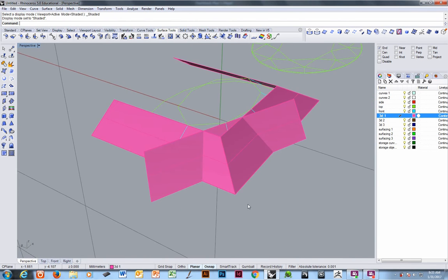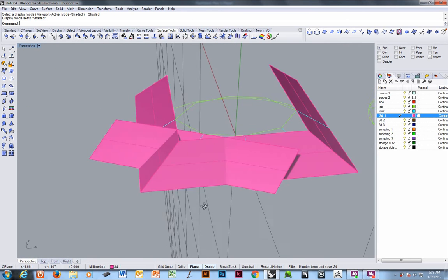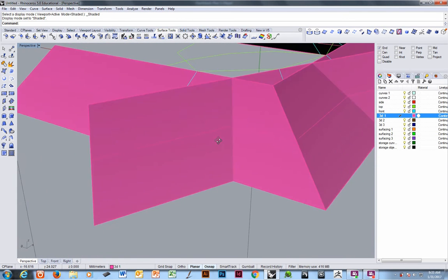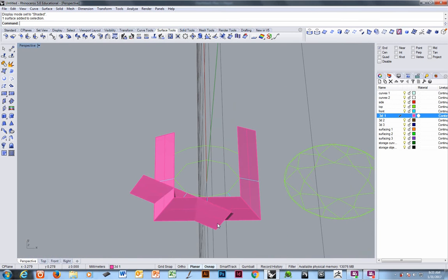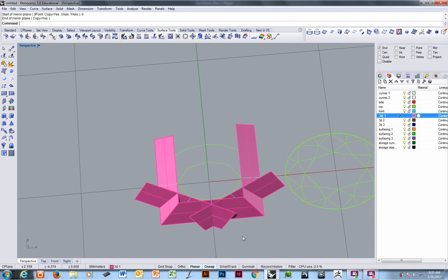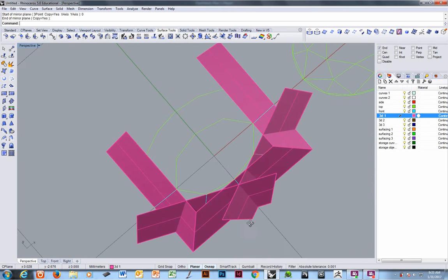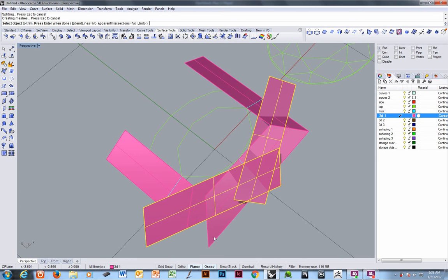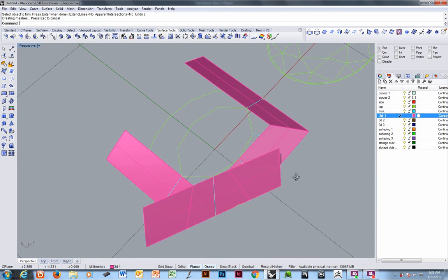Okay. The challenge is, since that's at an oblique angle, that the surface might not end up being a good intersection, but it is. It looks good. So mirror it over. By good intersection, I meant it may not be able to trim against the other surfaces, which is important right now. And that's what I'll do. I'll use this surface to trim off here and here.